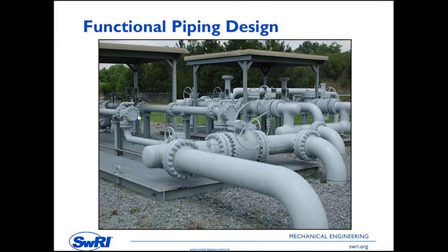But ideally, all of these ultrasonic meters that we install are flow calibrated before they go into service in the field. And what you would like to see is that the diagnostics from the ultrasonics replicate the condition that you had in flow calibration of the meter in the flow lab. So when you get to the field, it should look the same. In this case, this one did not. So there was an inferred bias condition that was causing measurement error.